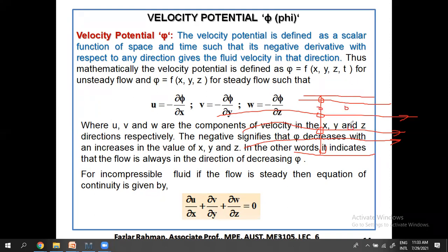But this one might travel right over here. This one, say, coming over here. So for all the particles, you might get this kind of profile. If you join all these lines, you get the velocity profile. In this velocity profile, in this portion only, all three fluid particles might have the same velocity. So this is the streamline, and we call it the velocity profile. But just think of this as the velocity line. Okay, so the definition of streamline we already learned, right?